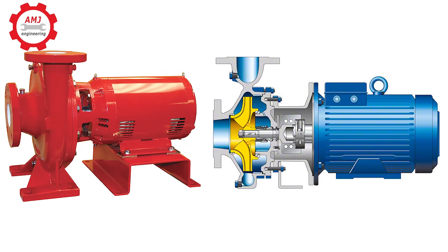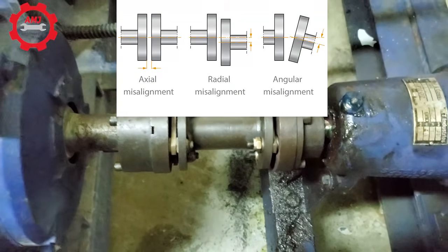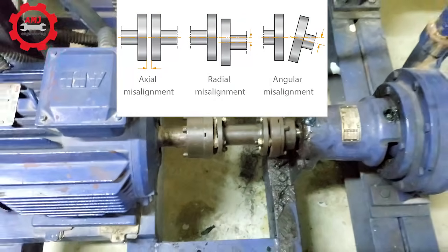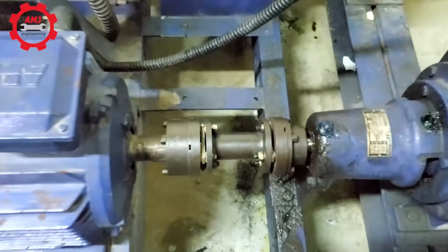A closed coupled pump has the impeller directly mounted to the motor shaft without any coupling in between. The benefit of using a closed coupled pump is that the alignment of the motor shaft to the impeller is fixed. However, a flexible coupled pump can become misaligned during maintenance. This can create issues if not properly reassembled by trained personnel.